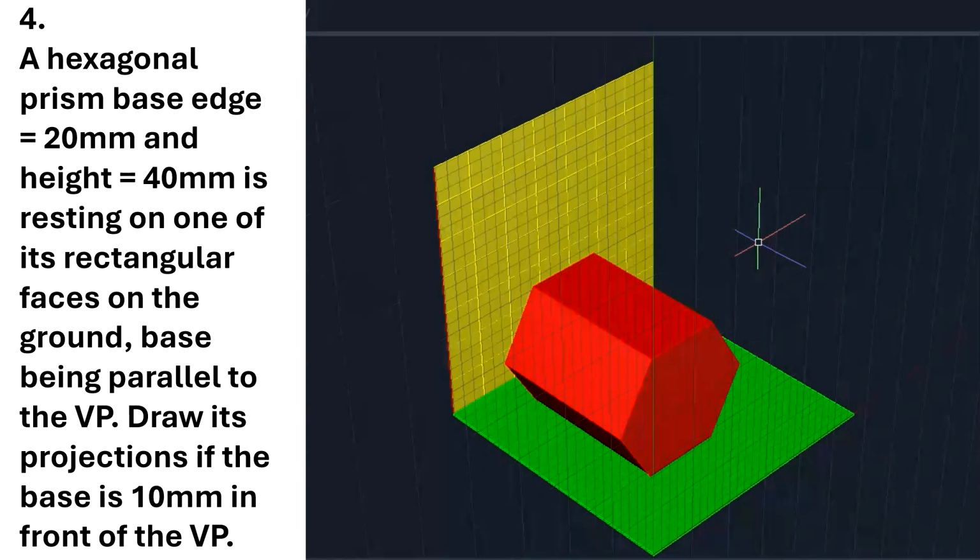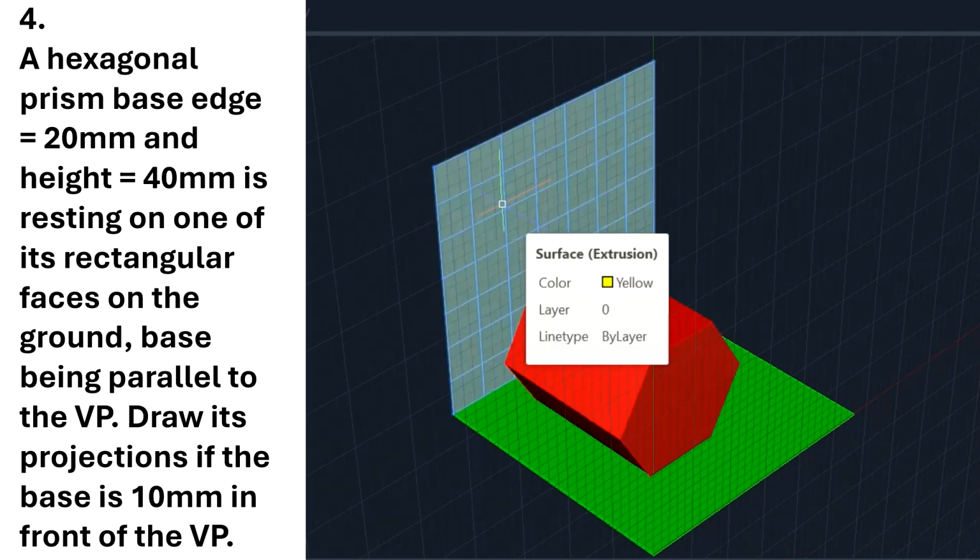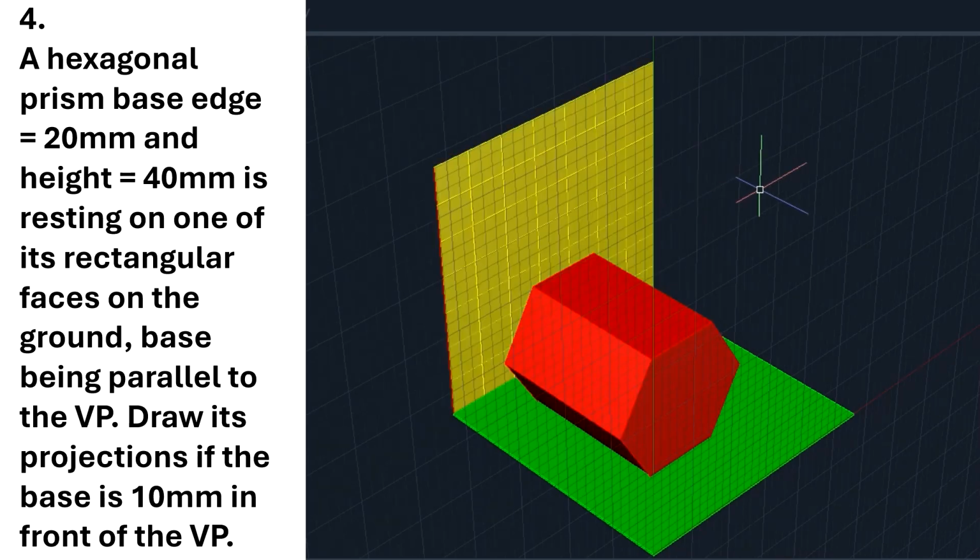Now if you carefully observe, the base is parallel to the vertical plane. When the base is parallel to the vertical plane, I need to first start with the view in which we can see the base. That means only in the front view can we see the base. So we start with the base, that is view 1.